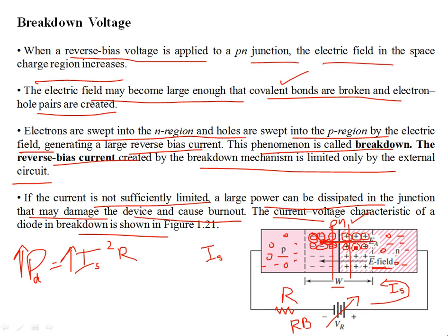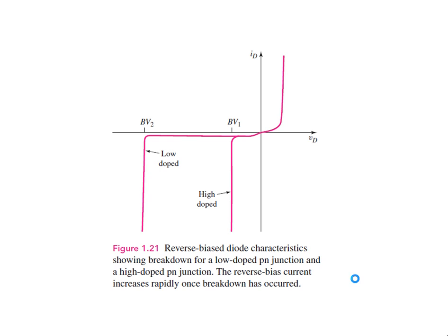So the field is volts per the length of the junction. The length of the junction is small, so the electric field is again very large. Due to the large electric field, you can have a larger current, and that reaches at much lower values than the conventional breakdown voltages.